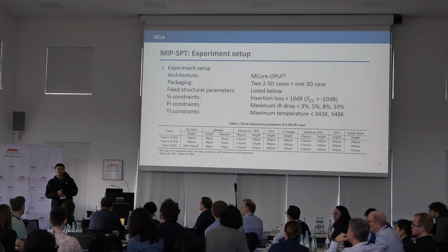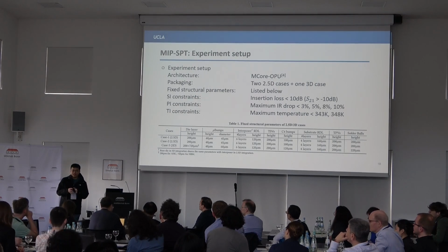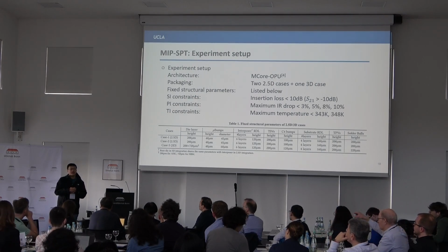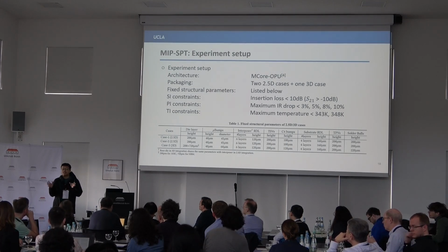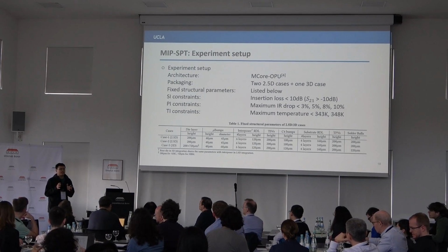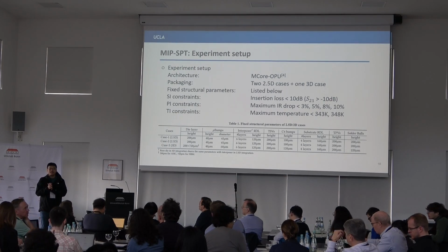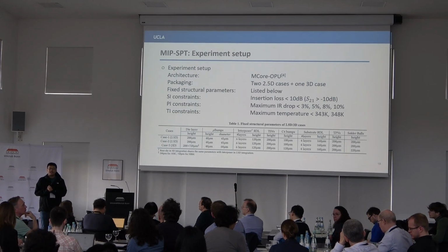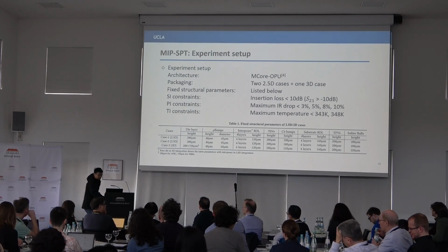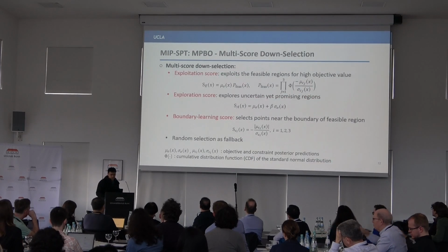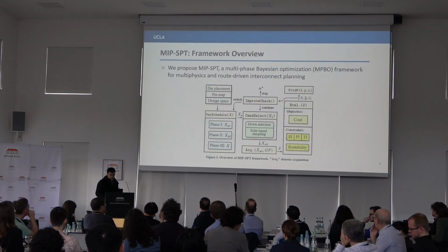Thank you for your question. In this work, we did not do backside PDN or backside power supply. We mainly work on the interconnects in the interposer. In the interposer, we use a relatively not so advanced technology. If you go to the very beginning of this presentation, you can see our modeling for 2.5D and 3D integration.